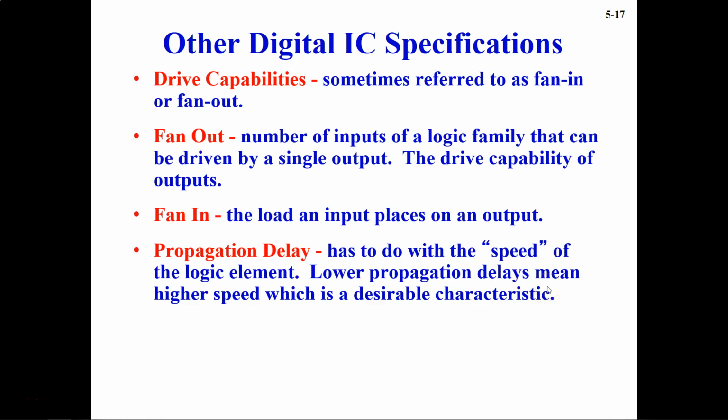For a standard TTL, the propagation delay is about 10 nanoseconds, compared with a propagation delay of between 30 to 50 nanoseconds for a 400 series CMOS IC.